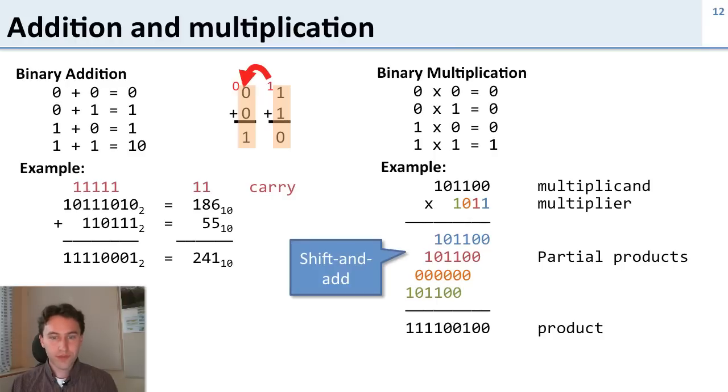So you'll notice that the multiply approach here is exactly what you do by hand. It's to shift over by one place and multiply by the digit in the multiplier. In the case of binary multiplication, multiplication is simpler because you're always either multiplying by 1, in which case you get the same thing as you had before, or 0, in which case you get all zeros, as you do with the orange value here.